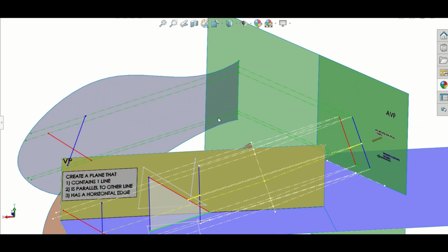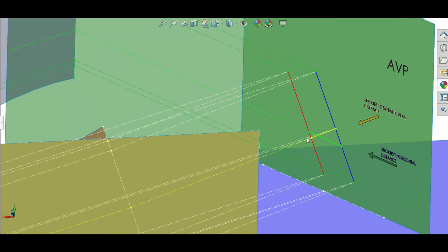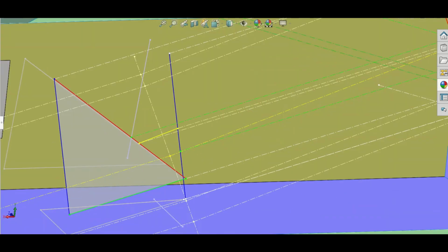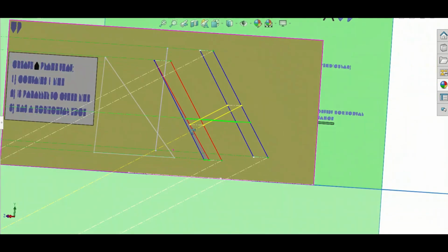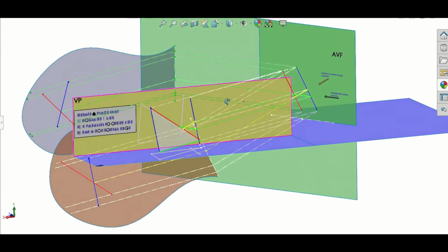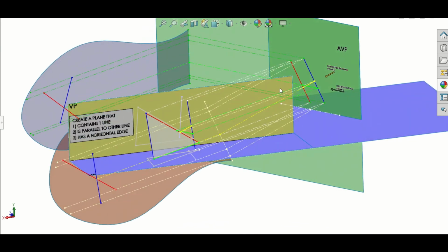So I'm going to take that back through my views. It comes from that point, it comes back up to the x2, y2. It comes right in along. And right here, that is the true length of the shortest horizontal distance projected down to plan. Now this is getting a bit busy down here. Projected down to plan and drawn, that is the shortest horizontal distance between those two lines. So the shortest distance there in yellow clearly is a good bit shorter line than this shortest horizontal distance. Now, if I haven't confused you yet, don't worry, I will. There's one more view still to come of this. But that is shortest horizontal distance.